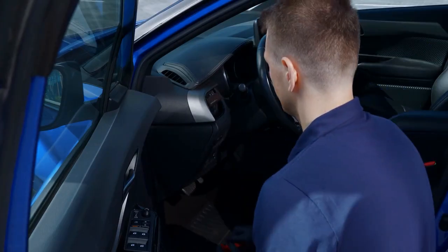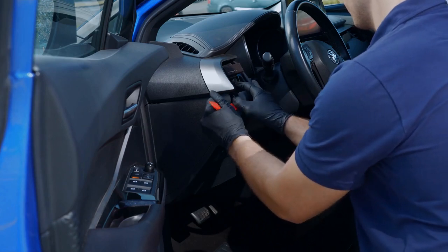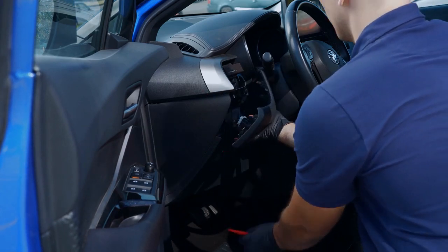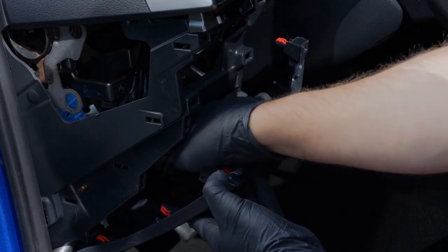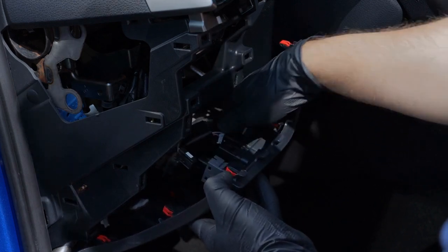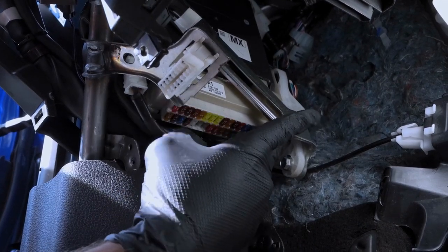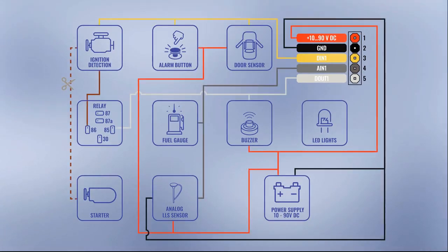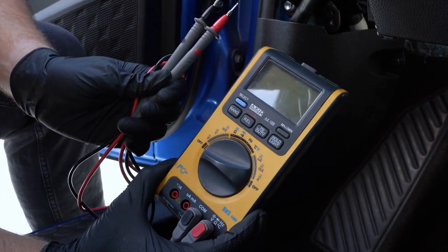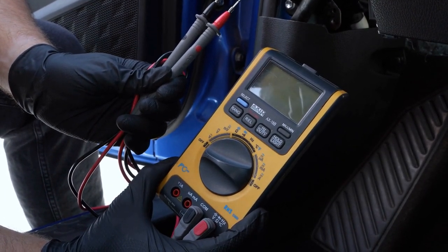Identify the location of the vehicle's fuse box. It's typically located under the driver's dashboard panel or passenger's glove box compartment. Before we begin connecting the FTC921 tracker, let's first take a closer look at the wiring diagram. It highlights which pins connect to specific components, helping you understand how to wire the device correctly. This time, we will demonstrate how to connect the power supply and the buzzer, an essential step in powering the device and ensuring proper operation.